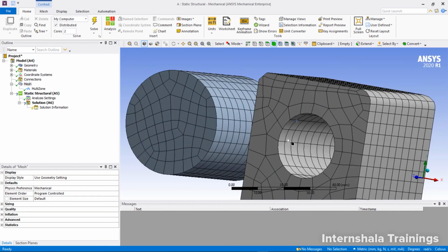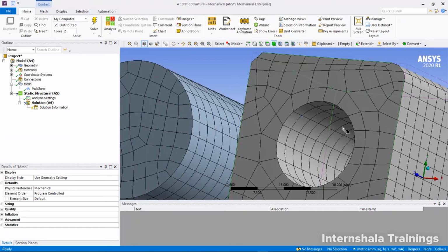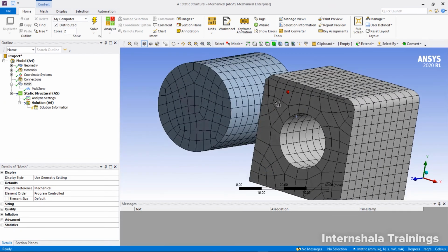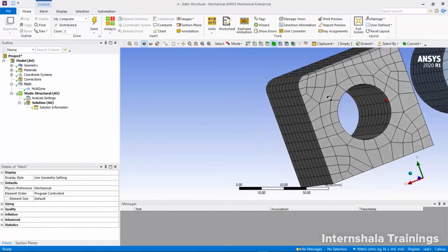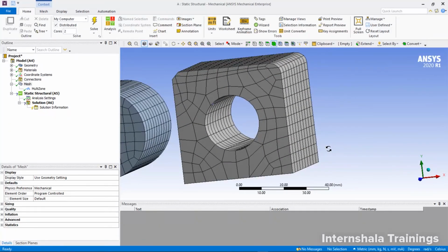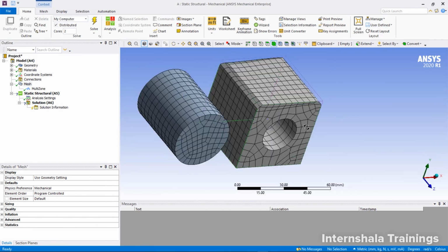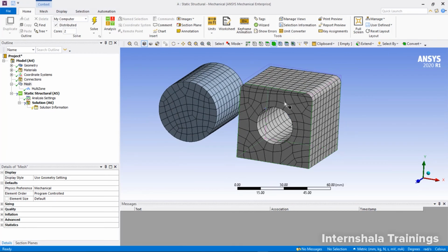If you are able to see, using the multi-zone meshing there is a possibility of creating good hexahedrals. What happened is it has created a good hexahedral structure here. Outside it was able to create hexahedral elements, so it has created them. But sometimes, in order to fill some gaps, it will fill up with tetrahedrons. It will be using both types of elements. And remember, for sweep mesh, this is not a simple object. For multi-zone meshing, it is somewhat a simple object.